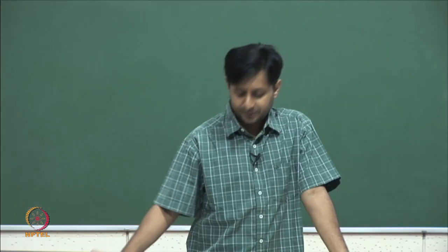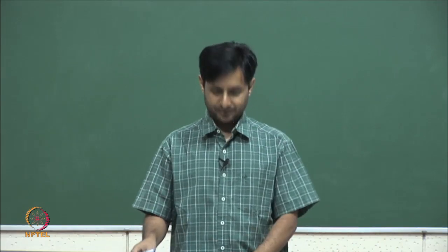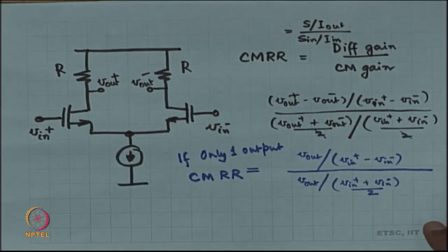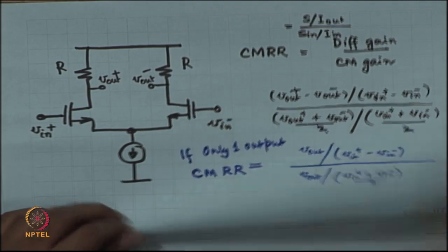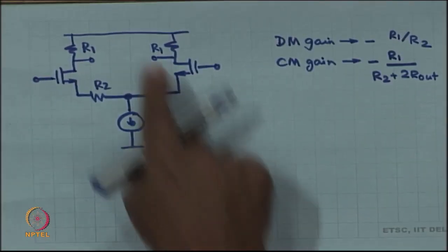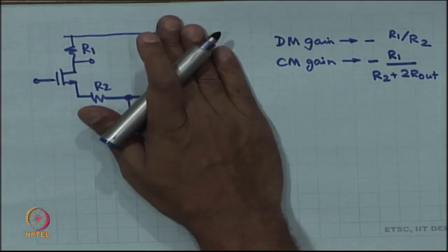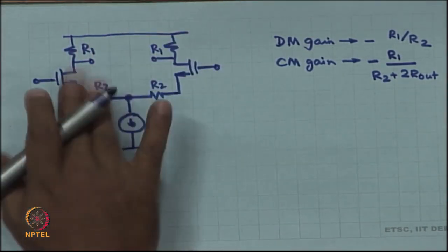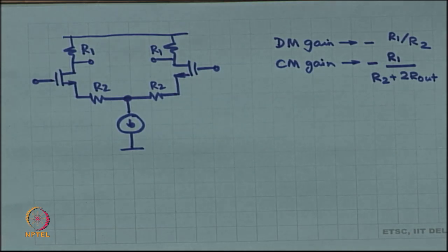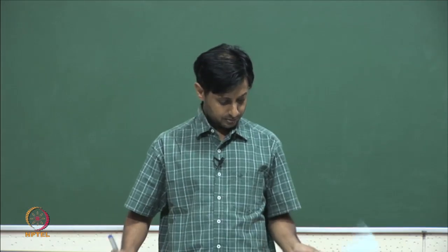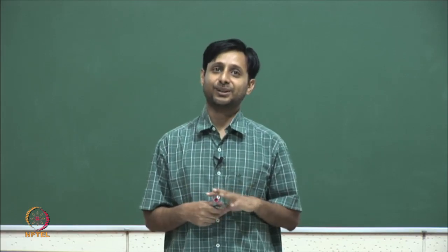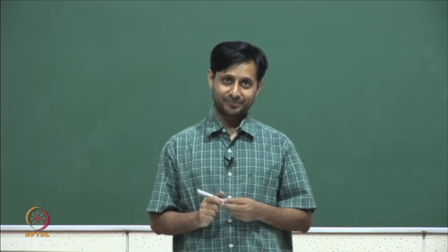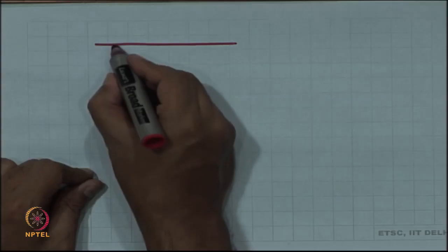All right. So, this is not the only differential circuit. For any other differential circuit, you identify the symmetry in the circuit and then analyze it. You see that this side is totally equal to the other side, and then you split it up into two halves and analyze the common mode and the differential mode. Now, we are going to look at the analysis of the same old differential circuit in a different way, and this is important.